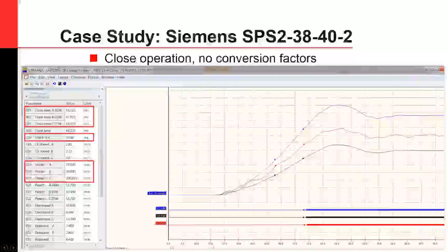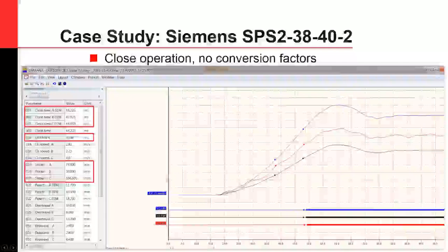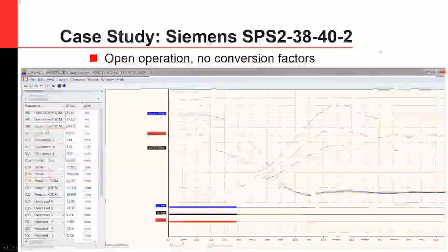And then stroke C, you'll see, is 106.5 millimeters. So all three times are correct, but we have very different strokes. And of course, from this, we're going to get very different velocities as well: 2.81, 2.23, 4.07. So it looks quite odd if you compare all these. And I will mention, I'm not using any conversion factors here. I'm just making a direct measurement.